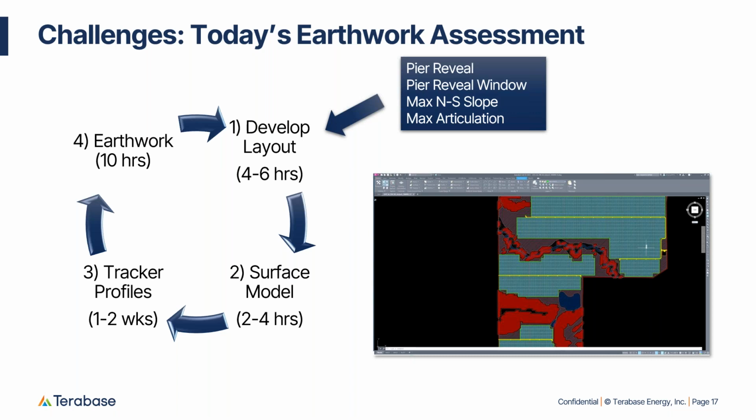The reason that this takes so much time, it's not in step with traditional volume calculations, is because in cases of a substation or a road or some drainage feature, those features have uniform cross sections, and it's quite easy to estimate what the earthwork is for those. Where within the arrays, it's very hard to do that in an easy way.